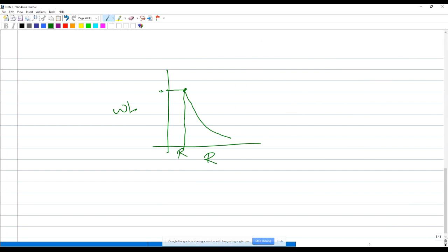And how much current will be drawn from the coil onto the sample surface will depend on the conductivity of the sample, right? So if the conductivity of the sample is more, that obviously means more current will be flowing on the surface of the sample, right? So that means it will draw more current from the coil.